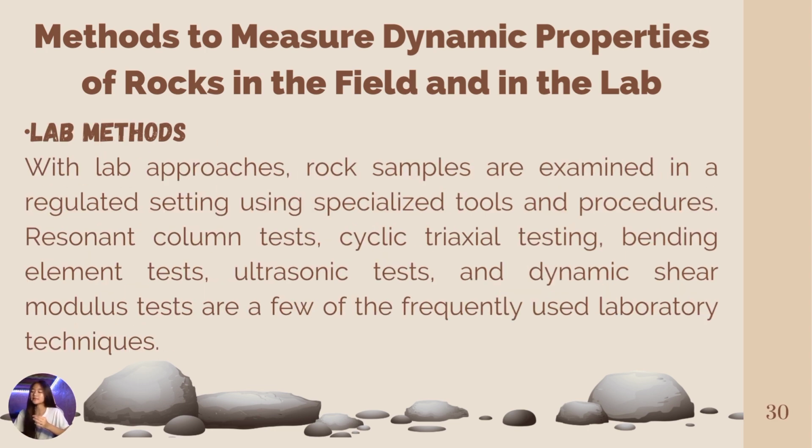So next is the lab method. With lab approaches, rock samples are examined in a regulated setting using specialized tools and procedures. Resonant column tests, cyclic triaxial testing, bending element tests, ultrasonic tests, and dynamic shear modulus tests are few of the frequently used laboratory techniques.